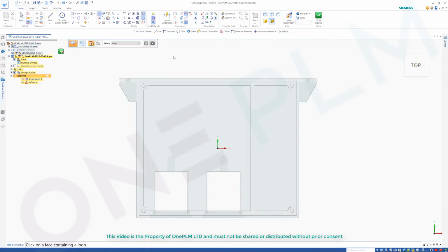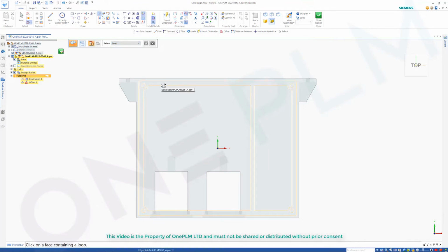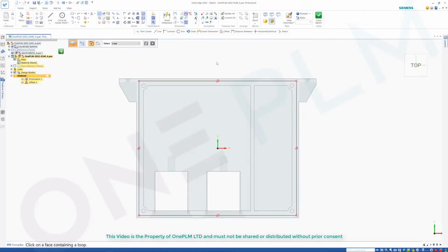So I'm going to use Projector Sketch. I've turned off my option on there, so you're wondering why that doesn't come up. I've just turned this little option off because I don't tend to use that very often. And we've got our different settings. We can go down. So this one, we want the outside loop of the face. So we can use the loop option. Click on the face and then click on the loop that we want. We can see that's going to highlight in orange. And then green tick or right mouse button to accept that. So we've now relinked those components on there.